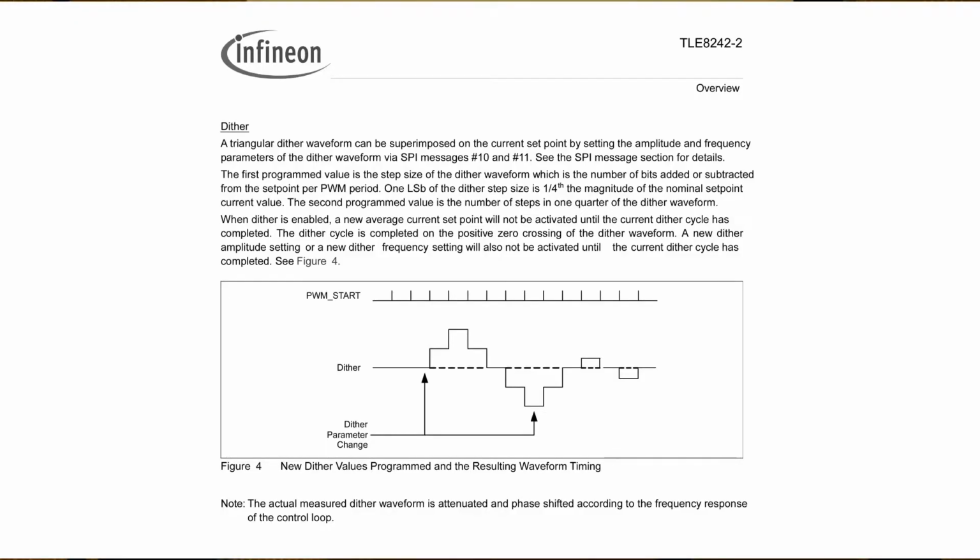A feature of the USD-II chip, shared by other modern chips, is the ability to apply a so-called dither waveform on top of the DC solenoid current. This AC component of current, more like a sawtooth than a sinusoidal variation actually, allows the current to fluctuate above and below the average commanded current. Its purpose is to minimize stiction within the solenoid's valve mechanism, which if not mitigated by dither current, tends to resist moving smoothly to a newly commanded degree of opening.